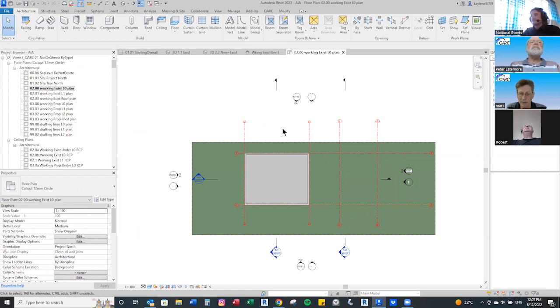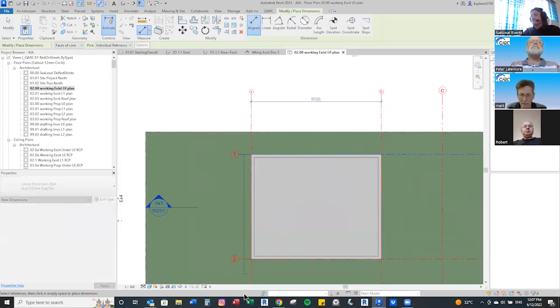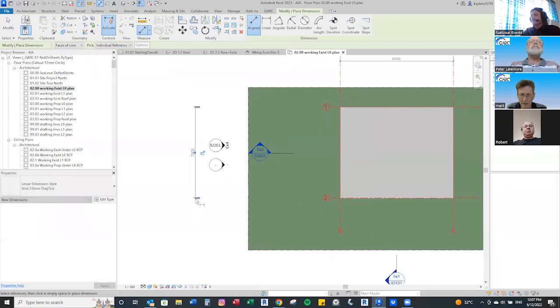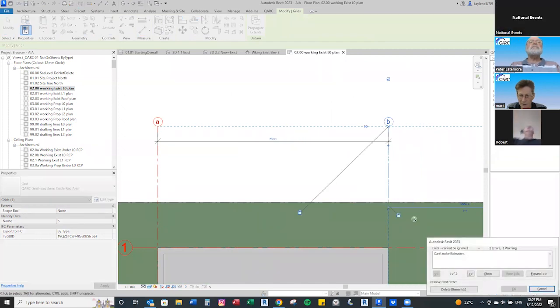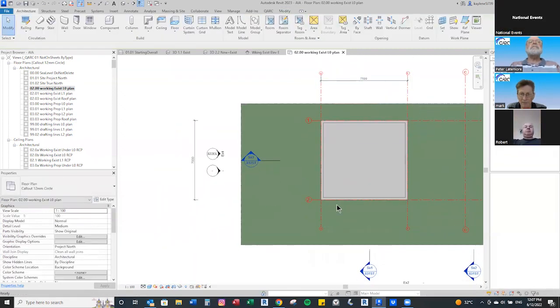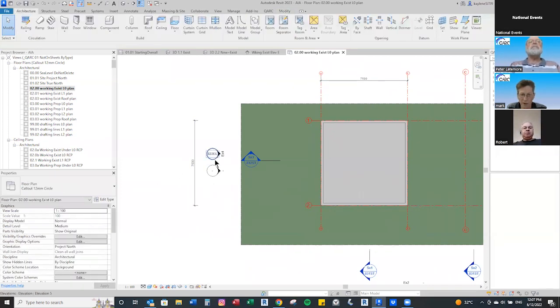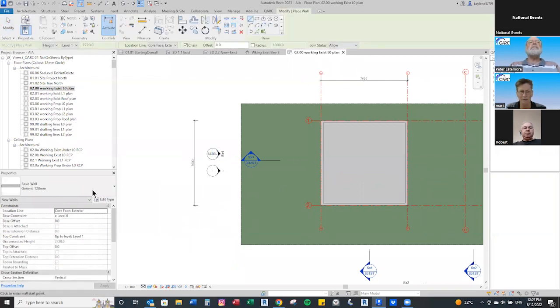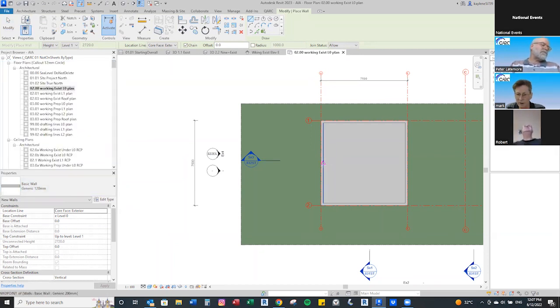So very quickly, you can have an existing building. If you've got some existing measurements, you can effectively get in there, click on the grids. And if you've got some on-site measurements, quickly add those, put in the measurements and adjust them, and the building will automatically adjust very, very quickly. And in no time, flattening up an existing building, done. The important thing about that is it's to do with phasing as well. So the phasing is set up on the sheets automatically, so it's very clear whether parts of the project are new walls or existing walls, and they're color coded and phased differently.